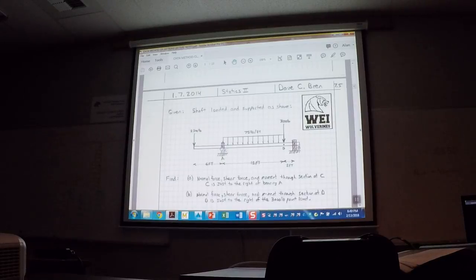But you know, I can't get moving until I figure out these reactions, because C has to be holding up something, and B has to be pushing up as well. There's nothing horizontal, but there's a whole bunch of vertical load coming down. C is basically holding up quite a bit. This collar has a lot more vertical load on it. This collar, I suspect, has a decent amount still, because there's a 3,000 pound point load pretty close to it. So I suspect B, I'm kind of curious to see which one of these, I think this one's gonna have a higher load. We'll see, right? We'll see.